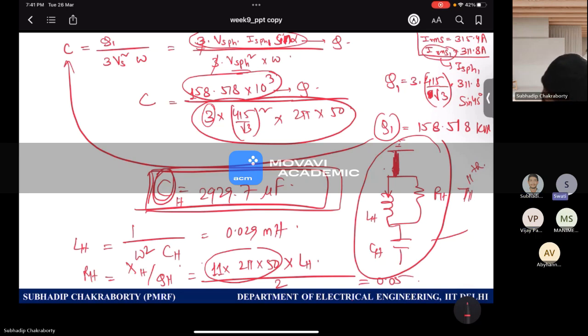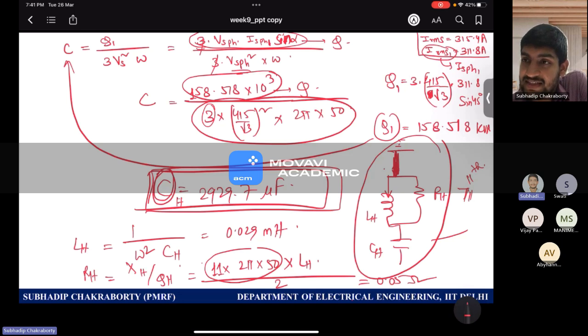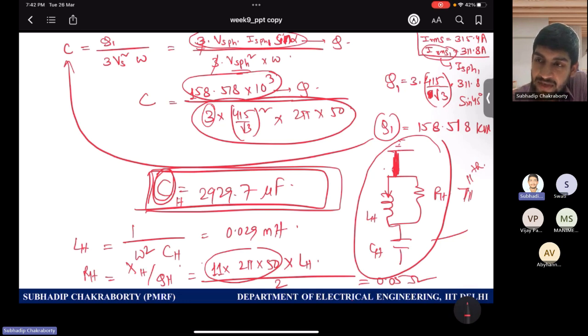Sir, I have a doubt. Tell me. Sir, with this method of calculation for C, we will always get the same C for every frequency filter. Correct. Why is it so? No, please be sure you are getting the same C, not the same XC. The reactance will be different, right? Please understand this. This is very important. Same value of C, but when you are at the power frequency level, that is at small omega, the capacitor will only dominate.